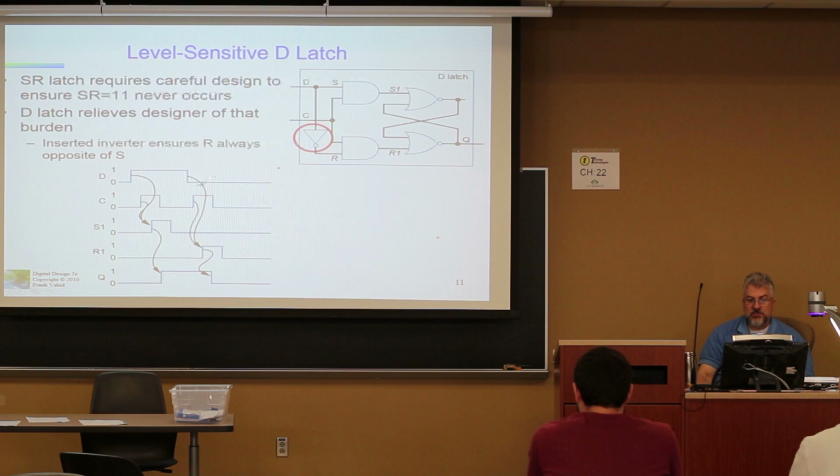One thing to note is that once you lower D, and you have D lower, and you introduce the clock again, then that causes R1 to basically clock as well, and it changes your Q down from 1 to 0. And this is the symbol for our D-latch, or what we call a D flip-flop.